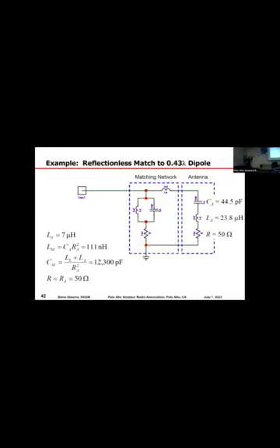to the right. And I don't need to use a transformer in this because I made those adjustments to the antenna lengths. If I didn't make those adjustments to the antenna lengths, then I would have to put that ideal transformer, because I might end up with like R equals 80 or R equals 100. And I've got to use a transformer to bring it to a 50 ohm resistive value.